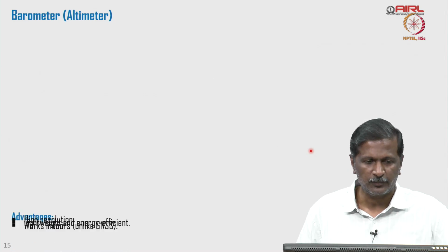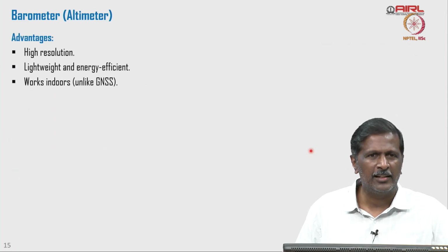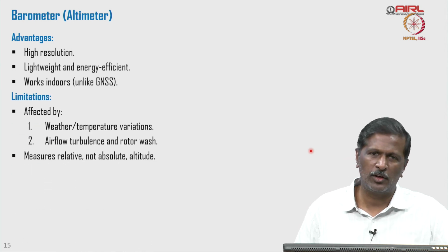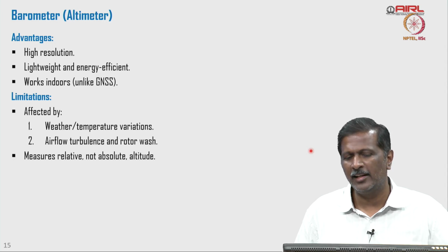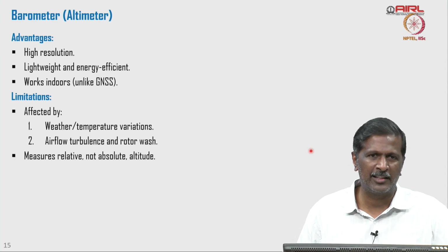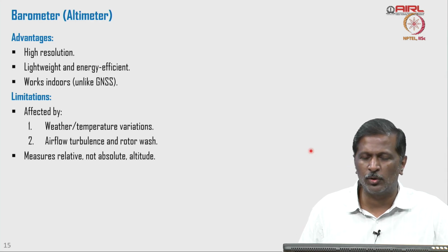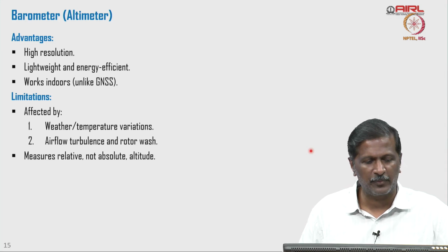Why do we use a barometer? It is high resolution, lightweight, and power efficient. It works both indoor and outdoor. The problem is that weather and temperature variations affect this. It is very sensitive to weather and temperature variations. Turbulence, and sometimes the rotor downwash, will also affect the measurements significantly, right.